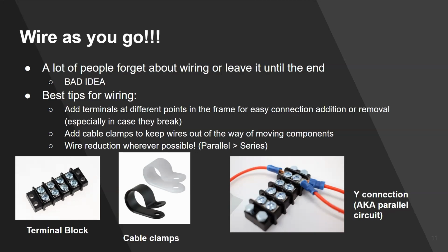parallel and series. The one thing I will say is, for those of you who know about old school Christmas tree lights, those lights were in series. The positive from one thing was connected to the negative of the other, so the current was just going in one straight line through every single component. If one single thing breaks, everything breaks.